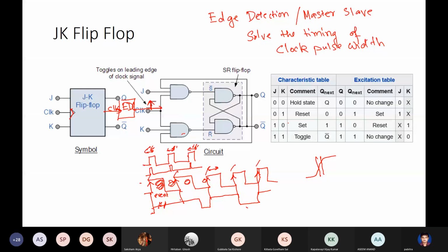The gated JK latch with the enable input is exactly the same. And again, if you forget the enable input, it's again the simple excitation circuit. So this will repeat depending on enable. This is the JK table. So this entire thing is for enable. If enable is 0, it's just the previous state, and enable again is the output of the edge detection circuit.